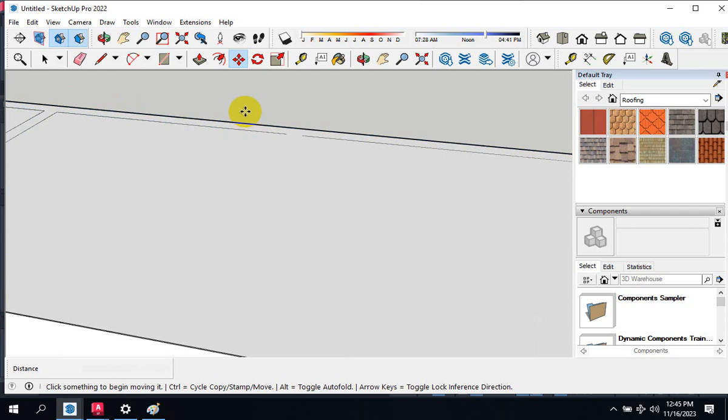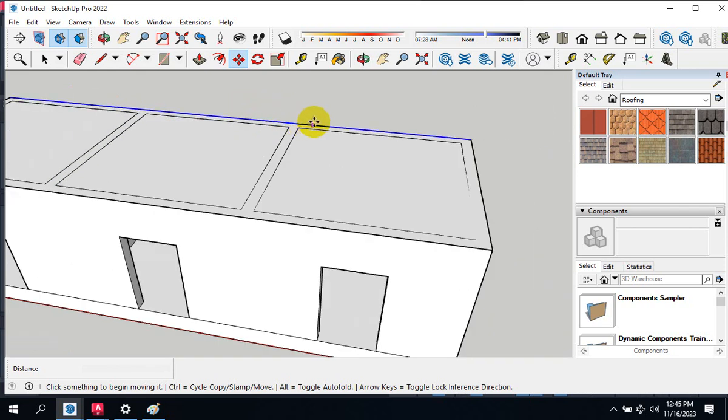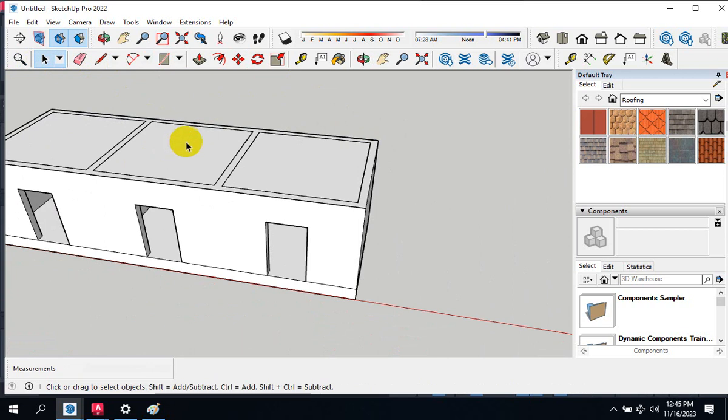The lines are because of the thickness. Offset? Yeah, I think then you better offset it by 230, because I see it inside the block work. Inside the block. Yeah, you can offset. You are right.